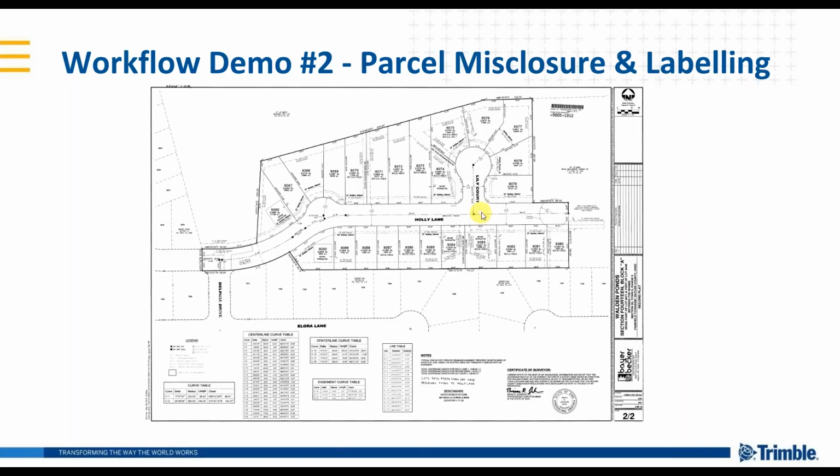The first thing I would do when I got to the site is take the lot that I was building on. For my demo, I'll be doing 9,076, this one right here. I'd calculate the boundary of the parcel to make sure that it closed properly. Occasionally I'd find one that didn't, and at that point it made my day's work quite easy, because I would send the plan back and ask for something better. It was a little bit labor involved. I'd use my HP calculator and go through and calculate it out. Then I'd inverse between my start point and my end point.